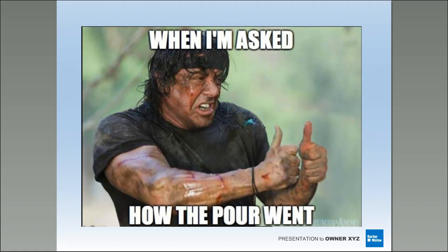I would purposely, and we do this a lot, purposely throw a flaw in there, especially on a job that we're polishing. I just did one about a month ago, and the polisher came out and said, I want you to put me a crack there, put a bump in there, and throw a cigarette butt in there. So we're going to show them how we're going to deal with all that. Don't make it pretty. Make it realistic because you're going to live with it, and show them the defects and show them how you fix the defects. That's a great point there, Jeff. Excellent point.